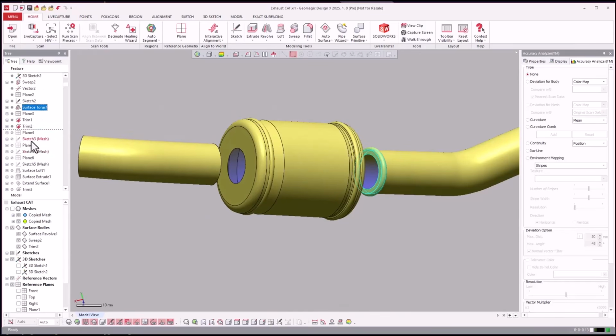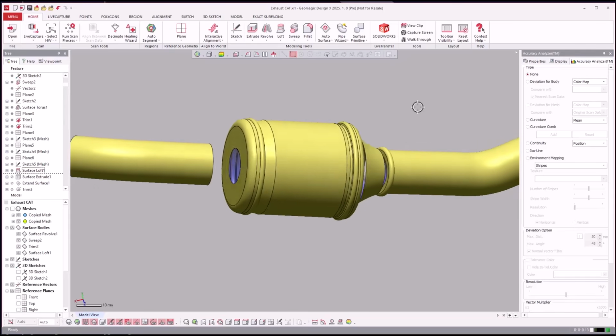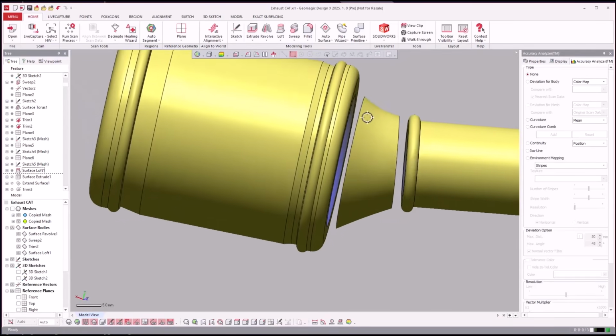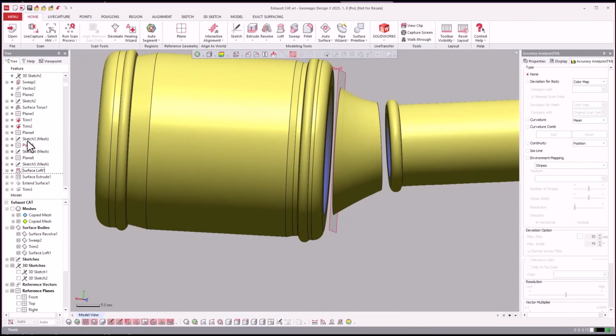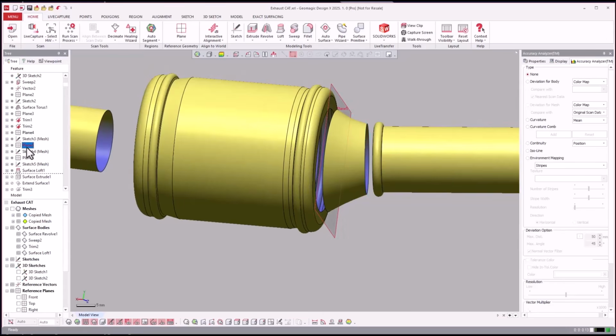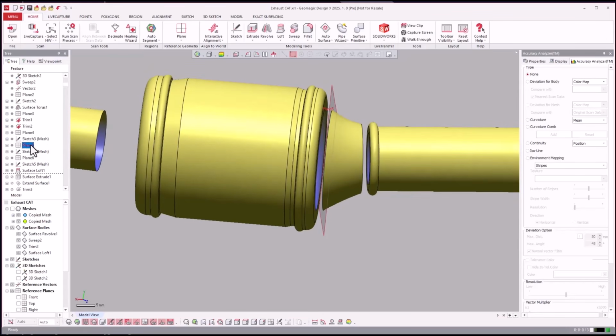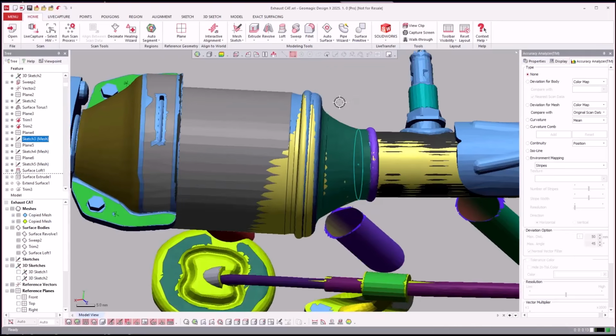And now we're going to jump into, here they did a loft wizard. So a surface loft, sorry, not a loft wizard. What they did, almost definitely they did an offset plane from here, right there. They did an offset plane there. They just drew two circle sketches right here and then lofted those together to create this shape.